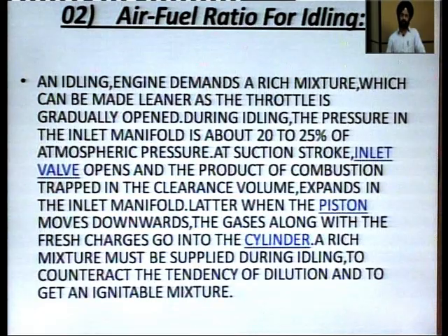Here it is written there. Later when the piston moves downwards, the gases along with the fresh charge go into the cylinder. A rich mixture must be supplied during idling to counteract the tendency of dilution and to get an ignitable mixture. So, what type of air fuel mixture is required during idling? A rich air fuel mixture. Why? Because it has to counteract the effect of dilution basically.